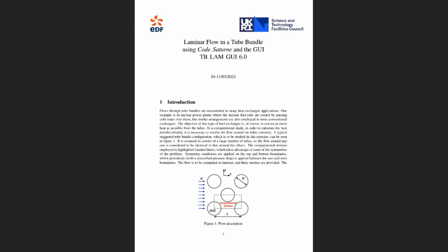So we start from the most basic domain, which is just what is dotted here in this picture. And we're going to just do a very simple laminar flow. You can run it either on your PC or in the virtual machine. The meshes that we are providing you are very, very small, so it's not going to be very heavy on your computing resources. And it's going to run fairly fast. We only do a few iterations, so it's just for you to learn how to create a case and run it.